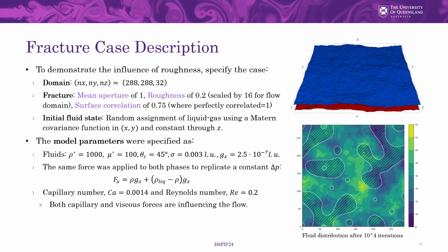The other interesting component here is that this is done in a fully periodic cell at the moment. This does create some issues in terms of the length of simulations that we have to run. But there are some interesting things around the body forces that you can apply to make sure you have a constant pressure differential across the system. That can be seen here by applying both an acceleration and a buoyancy term.